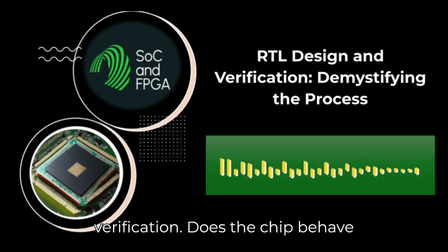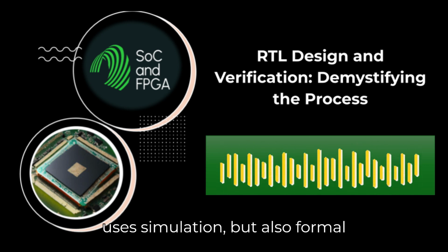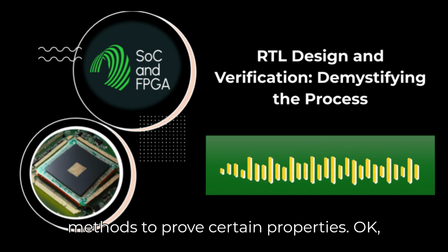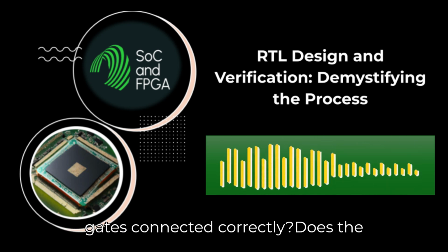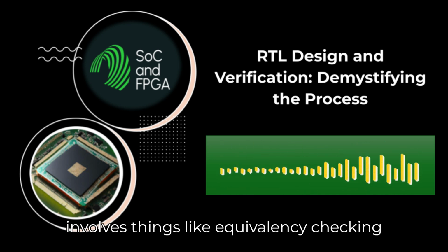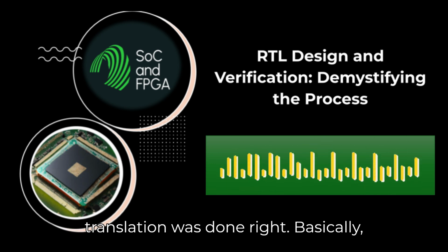You've got functional verification. Does the chip behave according to its specification? This often uses simulation, but also formal verification, which uses mathematical methods to prove certain properties. Okay, proving correctness mathematically. Right. Then there's logic verification. Are the gates connected correctly? Does the synthesized netlist match the RTL? This involves things like equivalency checking and static timing analysis. Checking the translation was done right.